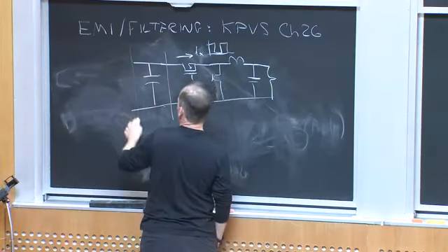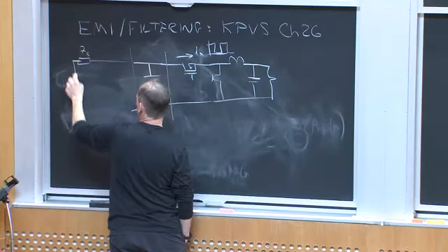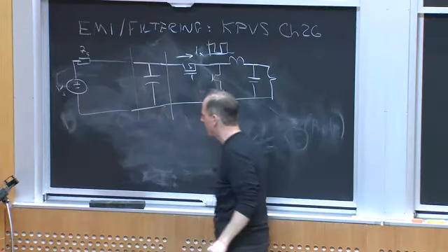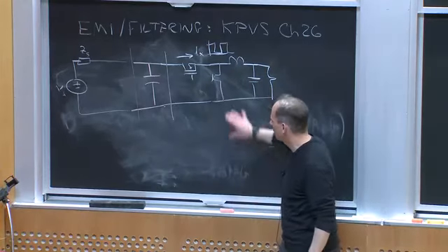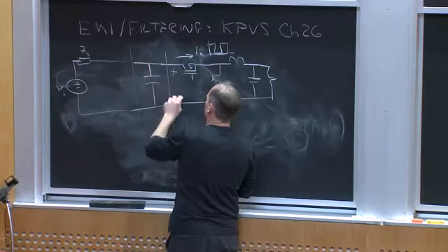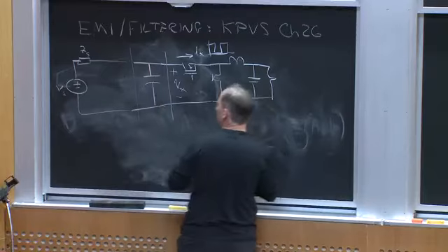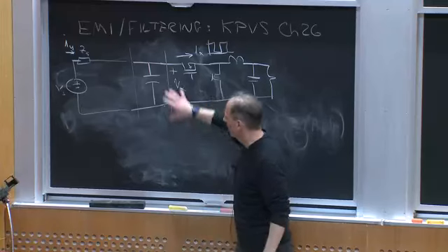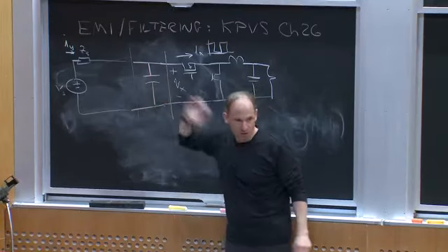And we said, well, if I just connected this up to some voltage source, V sub S, with a source impedance, Z sub S, I would probably run into trouble with repeatability, because depending upon what Z sub S looked like, I would get different voltages Vx, and maybe I'll call this current I sub Y, on the other side of the filter. And so it's kind of problematic from a repeatability point of view.